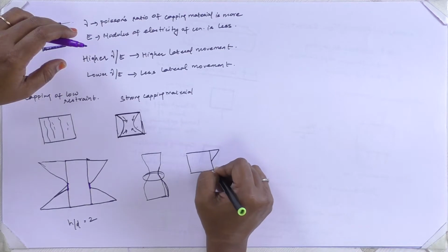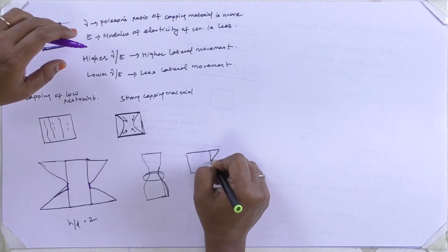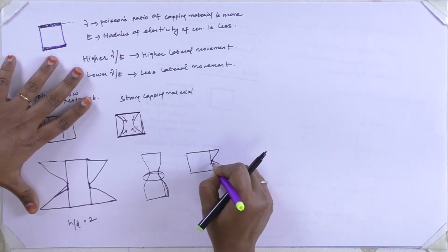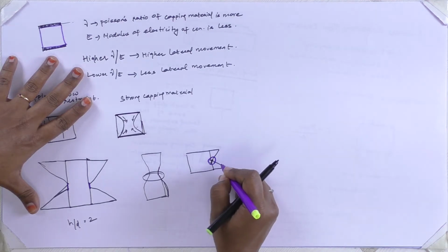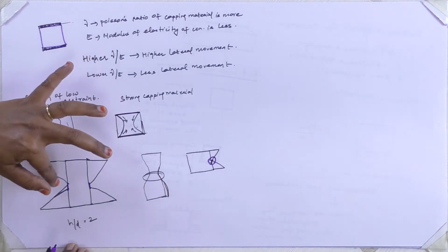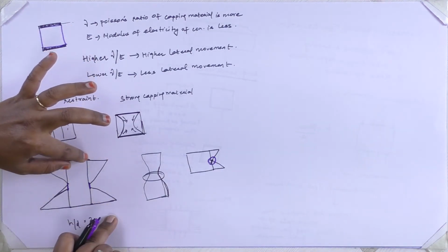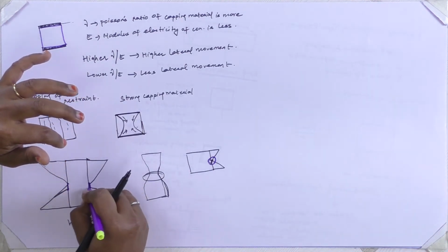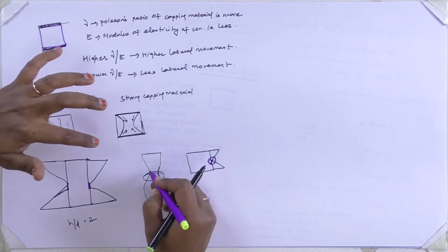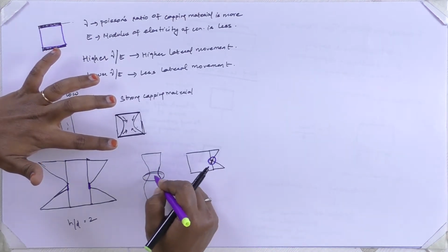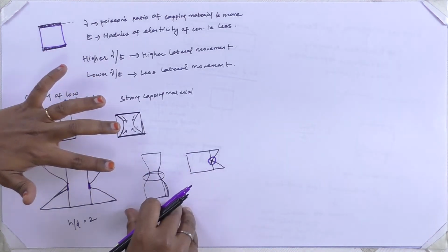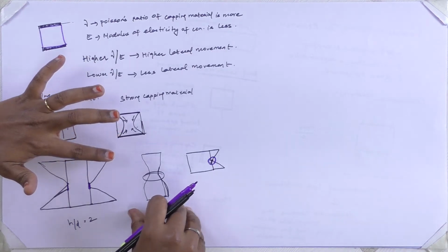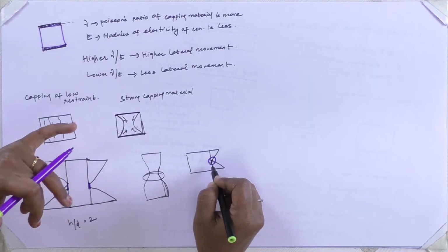In case of cubes, the Platen effect will be like this. Here we'll have some sort of overlapping, whereas for cylinders that overlapping will not be there and some portion will be left out, and that's the reason why we get a failure pattern in this manner. Why are we getting this overlap?